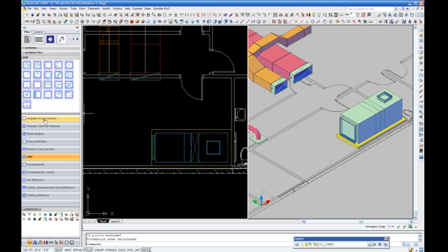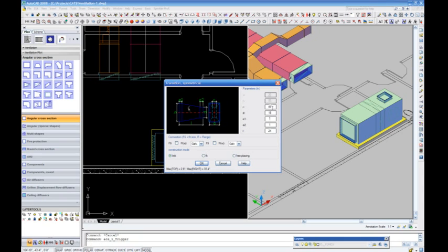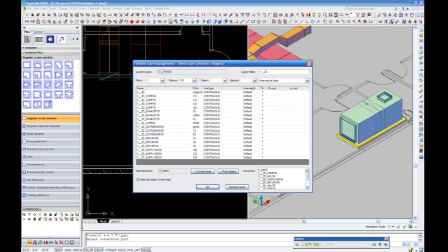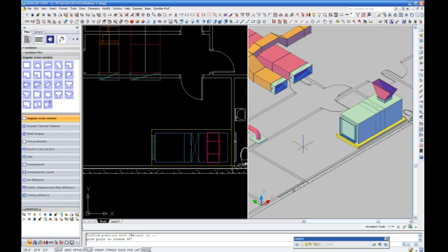The pad is placed. We will begin our design of the ductwork connections from the unit connections to the fire dampers. Here you will view the means of connection that are unique to the C.A.T.S software product. We will begin by placing a transition on the supply air duct flexible connection. By selecting the flex connector, the flexible layer management appears, prompting us to select another layer for supply air duct within the mechanical room.